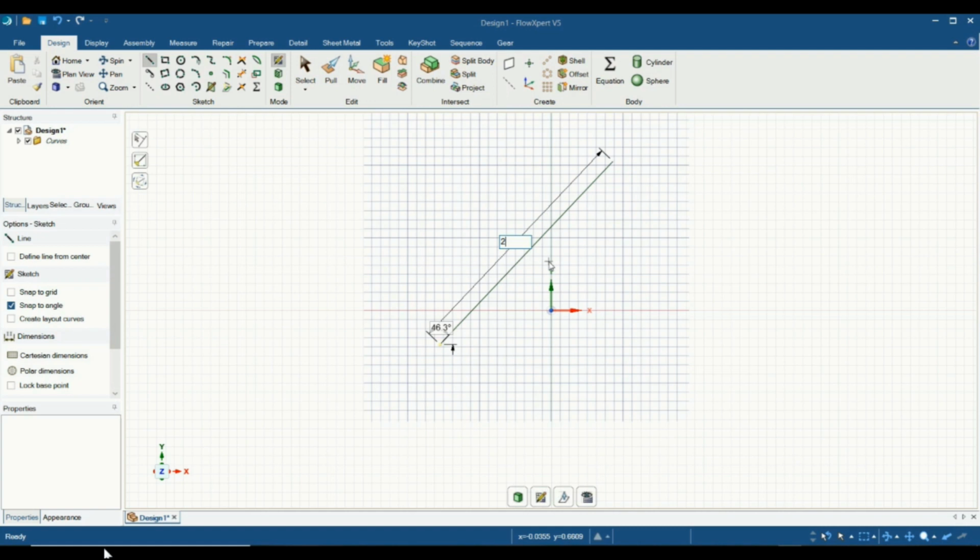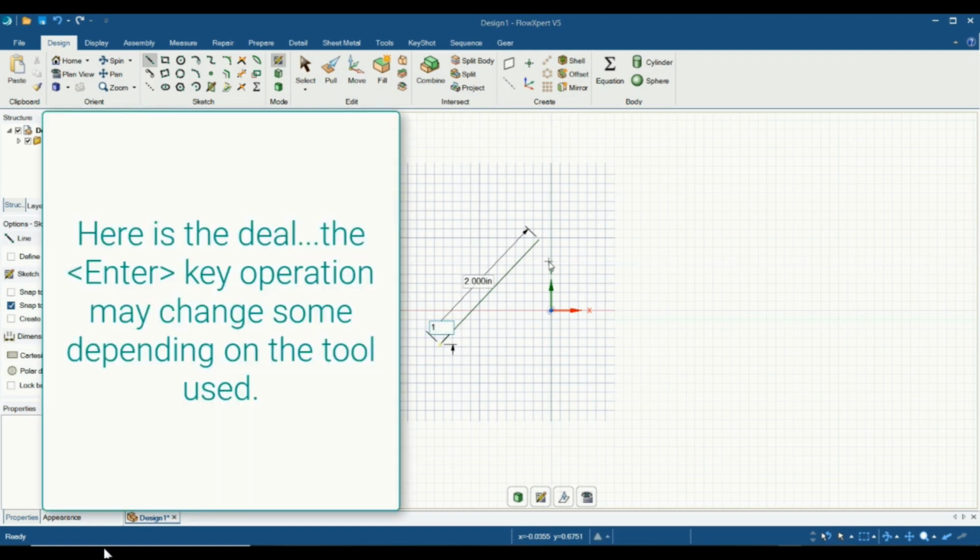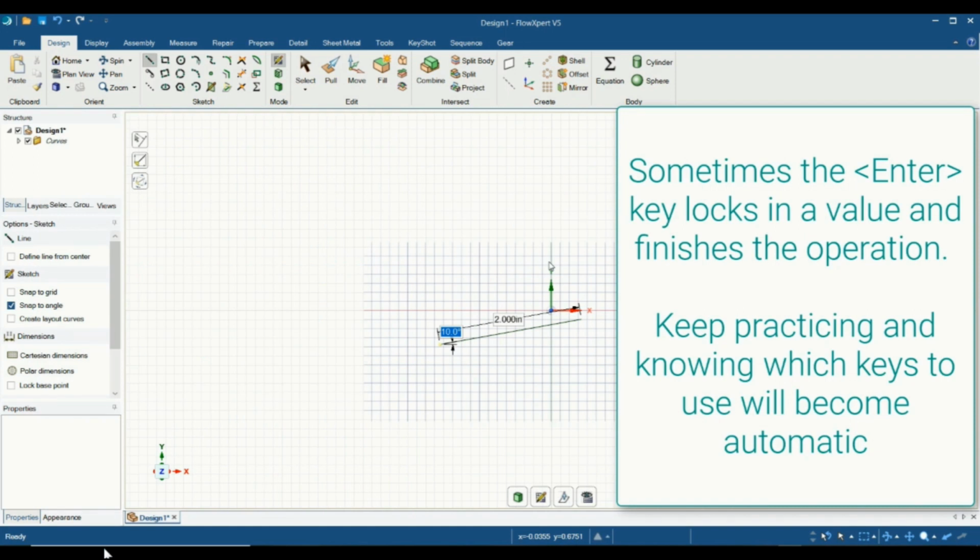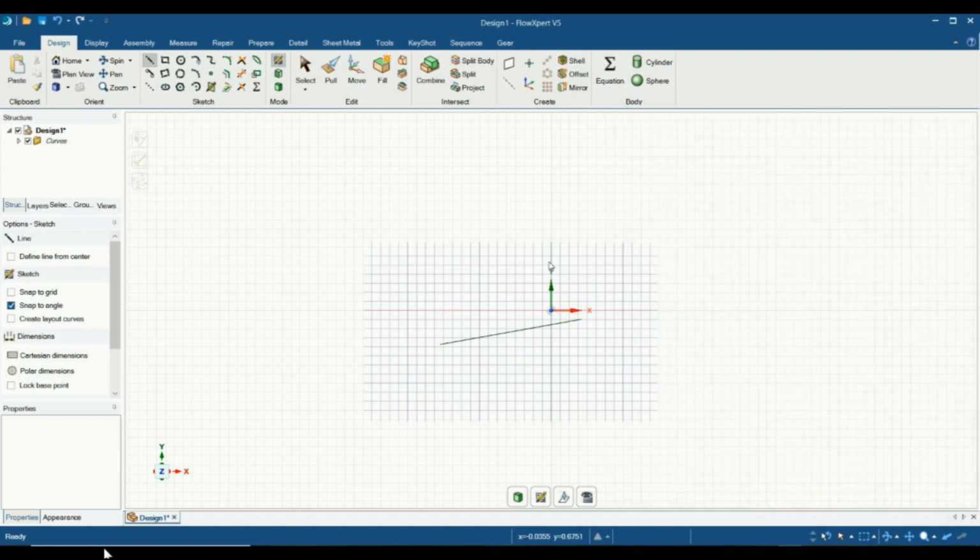If you change the length parameter and press the Tab key, the change takes effect immediately and you move to the other parameter. If you change a value and press the Enter key, the change takes effect, but you stay in the same parameter box. By using Tab and Enter, you can create the desired line. Pressing Escape or double-clicking ends the operation. Now we can draw a line of specific length and angle.